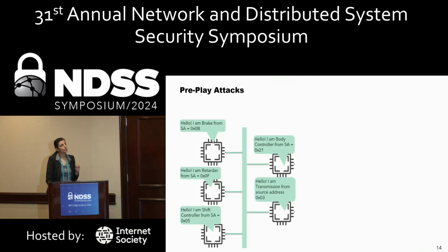This is a simple pre-play attack. Any controller application trying to participate on an SAE J1939 network goes through address arbitration based on the priority of the name field.